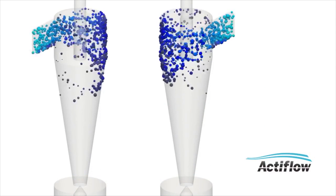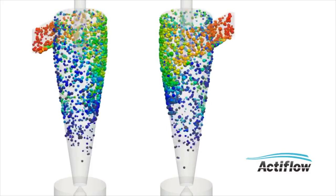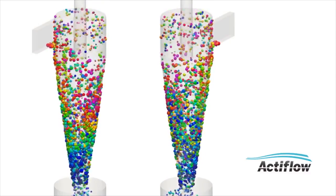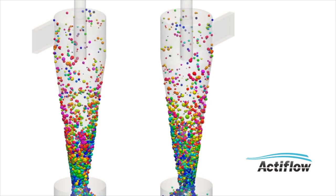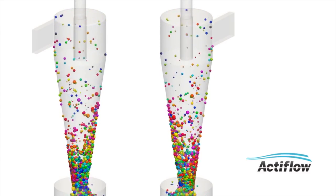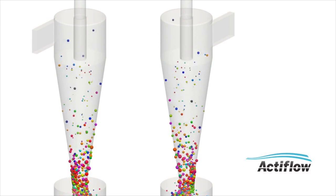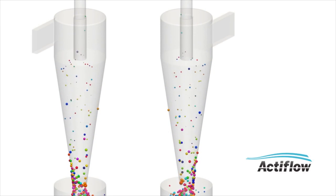For our design, we chose a reverse flow cyclone. This means that the inlet flows tangentially to the body, as shown in the simulation. Cyclone dimensions are crucial to ensure proper separation. It is clear that the larger particles separate easier, and the fine particles tend to stay suspended in the flowing vortex. To achieve proper separation, the outlet must drop into the body of the cyclone, below the inlet and above the conical section, to allow the vortex to flow properly.